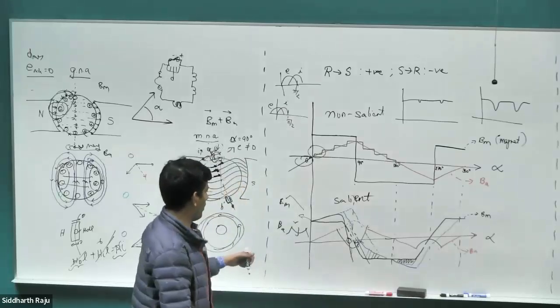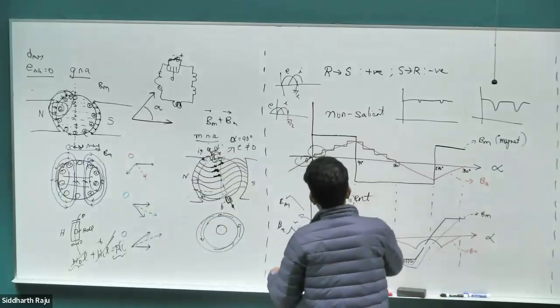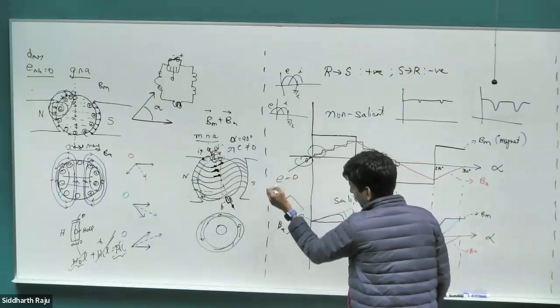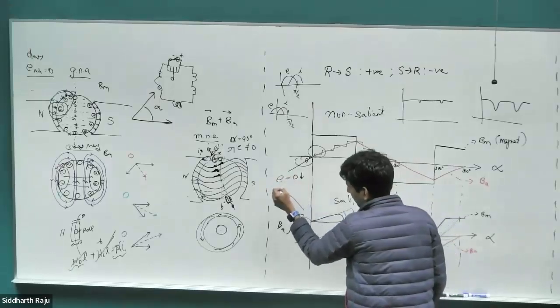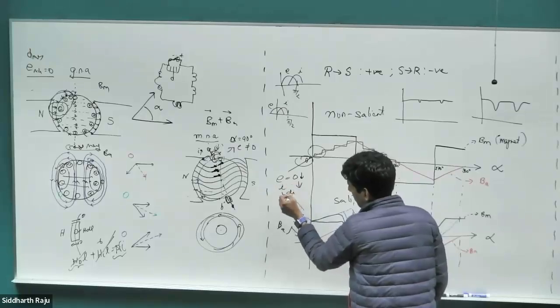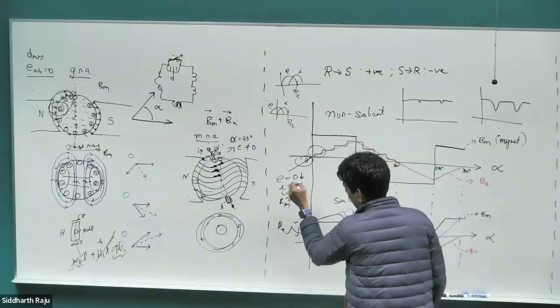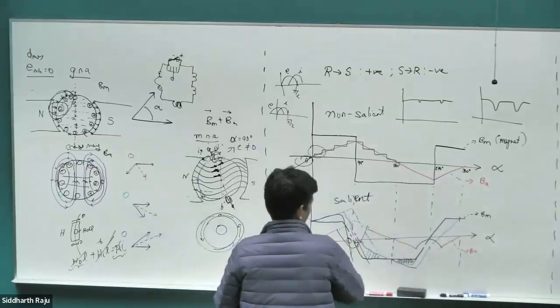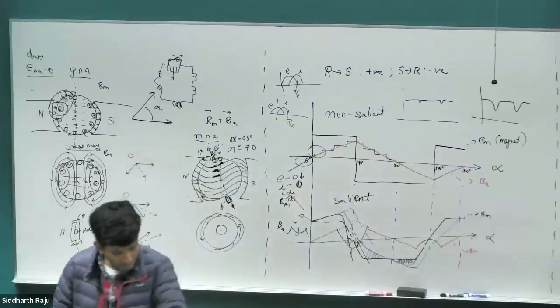All right, so interpoles will allow you to compensate not only for the effect of armature reaction, bringing E to 0, but it can also make E go negative so that the current goes to 0. So you can compensate for the LdI by dt effect. Right? Current goes to 0. So both of those can be achieved. So the final method that we saw is our compensation windings,